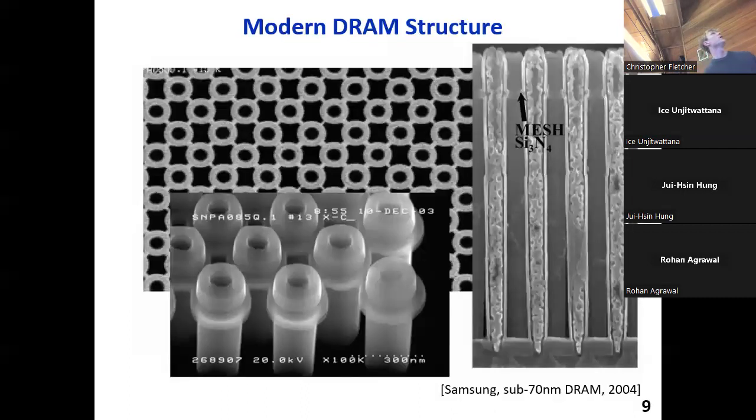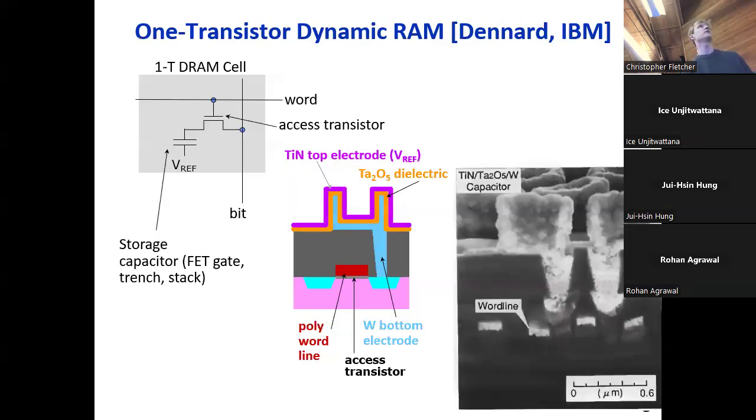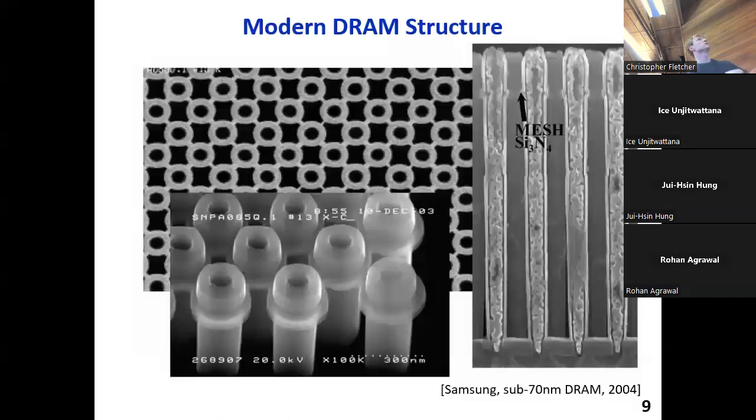And so modern DRAM cells look a little bit different. The first picture in the back is just an array of DRAM cells. I'm jumping a little bit ahead because I haven't spoken about what multiple DRAM cells look like, but imagine that these are two cells that are next to each other in an array, and the analogous picture is just this slightly differently oriented array. What's interesting here is the shapes of the capacitors look a little bit different.